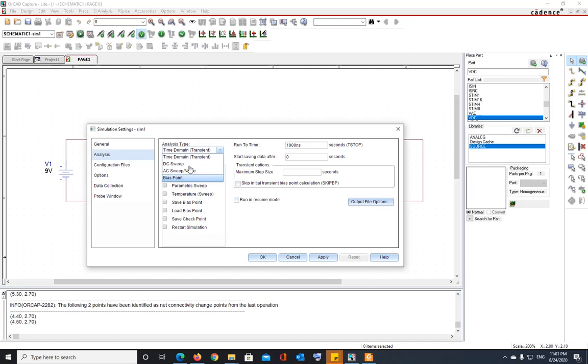And the last type of analysis is AC sweep or noise analysis. AC sweep is basically how the values, when I say values, I mean voltage, current, power, stuff like that, are going to change if you change the frequency of an input AC source. Let's say the power that we get at 60 hertz, 120 volt RMS, 110 volt RMS, right? Assume that you want to change the frequency. You don't want to keep it at 60 hertz. So you start with 1 hertz and then you start changing the frequency and you go all the way up to 1 kilohertz, 2 kilohertz, 1 megahertz.